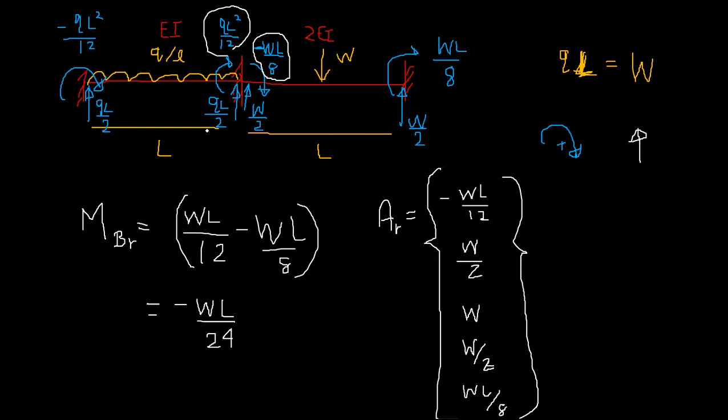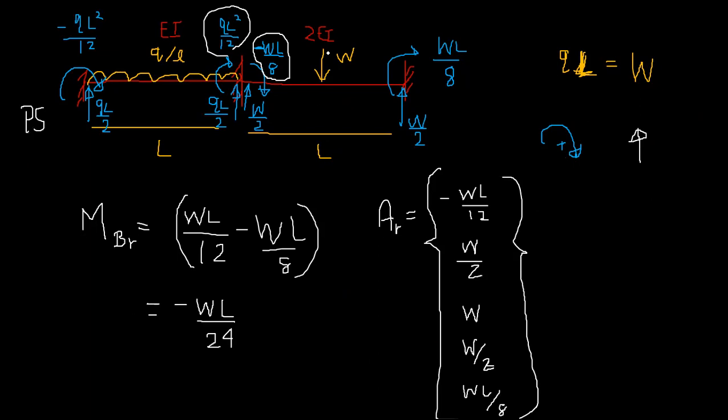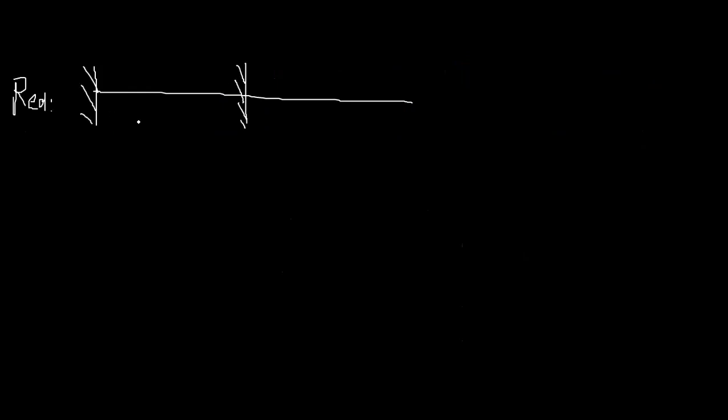Okay, so I now need to apply the displacement which I made 0, right? Since I have loading everything here, I can apply that to the structure without any loading, because I'm going to superimpose everything. I need to add the primary structure and redundant structure to get the final structure. So it's okay to have W in any of the stages. So fix everything, and with W I take everything, and then I can apply the unit displacement for the structure without any loading, right?